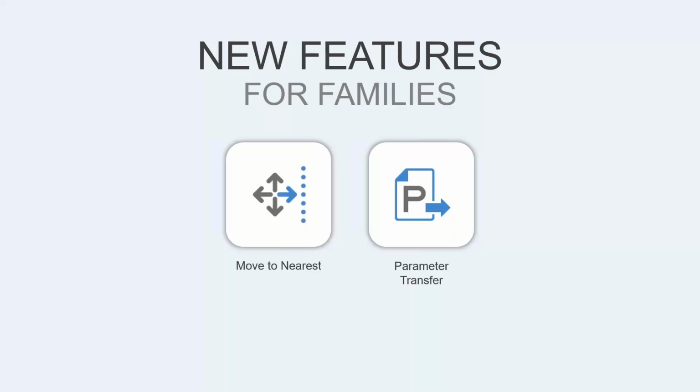And what's really great is you can set different settings for this. Do you want to align the entire grouping of features? Do you want to align each individual feature? Do you want to align it based off of the entire bounding box, the center point? And then you can also, which is my favorite part, specify an offset. This is really great if you need your elements to be a specific distance from another element. The example I will show is having all of my doors a certain distance away from the wall, right? Because when we place our doors or design our spaces, we always need the door a certain distance from the wall, and we want that to be consistent across our whole project.